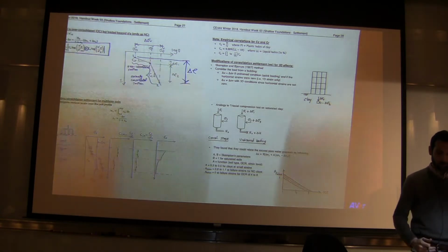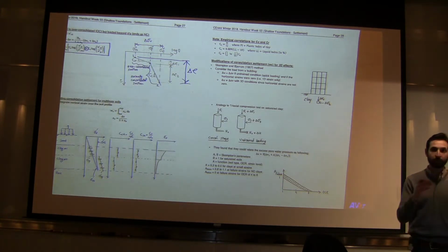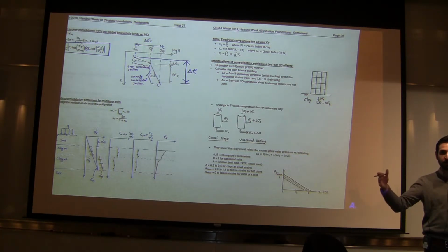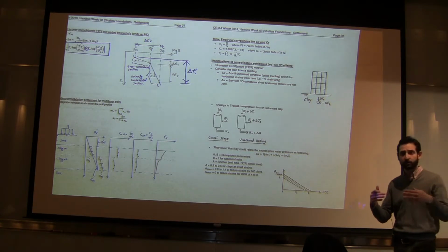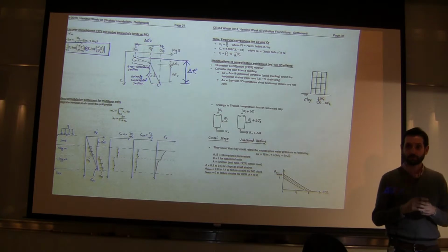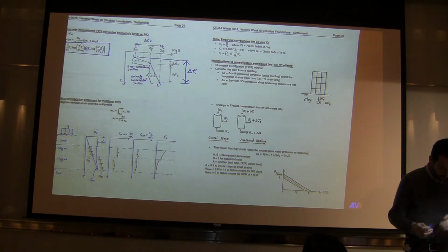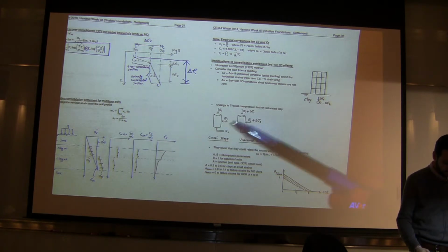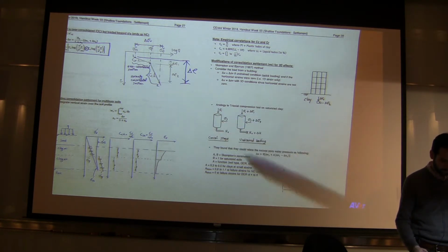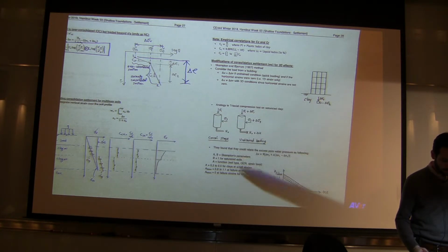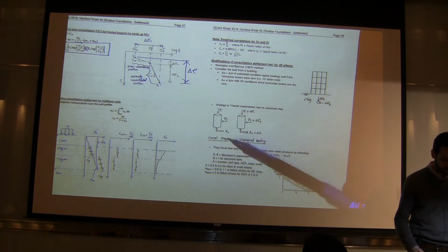And that's our whole purpose here: how to make this connection with the real world, where the soil consolidates in three dimensions and can expand laterally, to the results of consolidation tests that we get from lab tests with a rigid ring. So to do that, let's look at this triaxial test example here. That's a triaxial test under sigma 3 and sigma 1, and the pore water pressure is U naught.